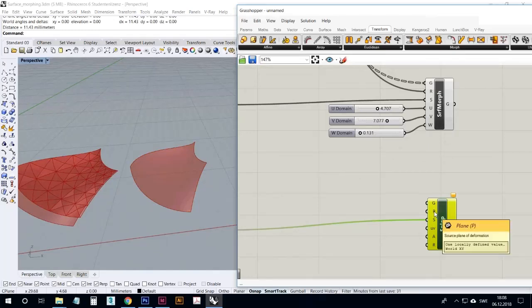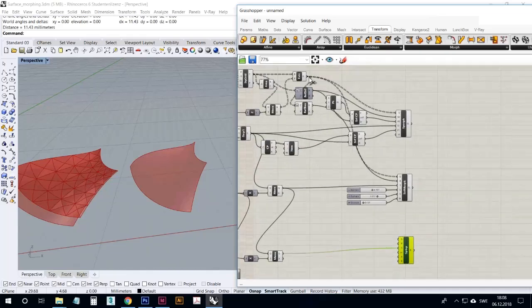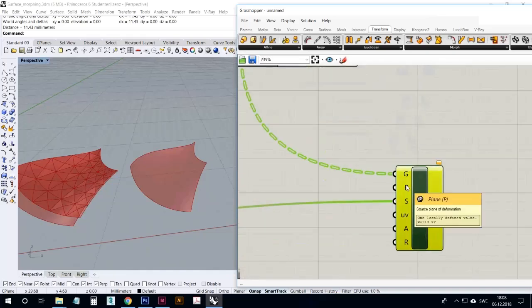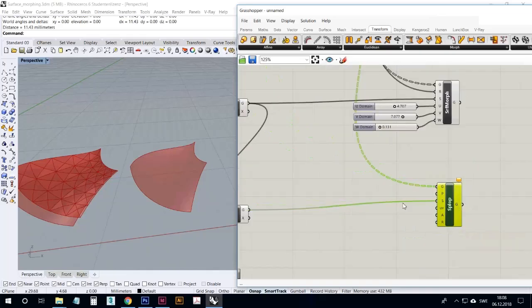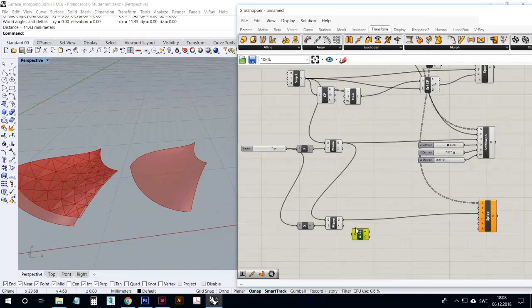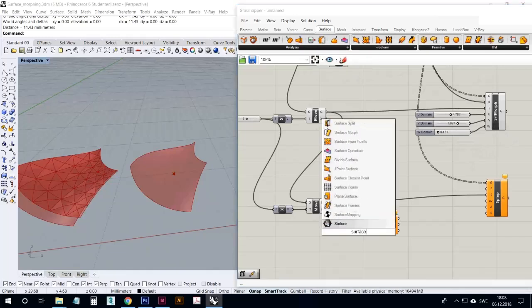So it's actually built in already, world XY, so we don't have to do anything there. It's already filled. What we have to do, of course, is to get our geometry. And like I said, the reference is already there. The target surface is already there. And then we need a point on the target surface. And we know how to do that. So we can take an area. Notice that I'm not copying that now. I'm doing it again just to show it. And here it is, surface closest point. You can also Google for it, so to say, or search for it. Surface closest point there.